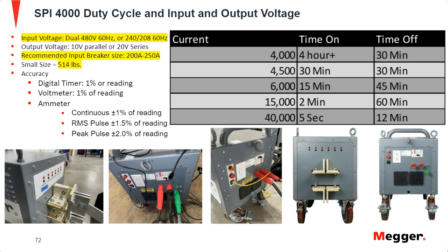So there's an overload. You don't want it to trip immediately. Say, for example, you're using the blow dryer in your bathroom. You just don't want the breaker to trip because the load suddenly went over the actual rating, and you want to give it a long time to see that overcurrent before it trips. And a short time, in the sense where you're going to start up a motor, there's going to be high inrush current. You don't want the breaker to trip. You want the breaker to, for a short time, allow that current to pass through.